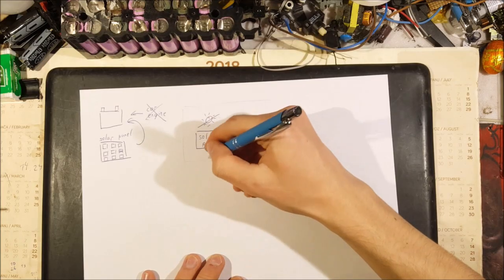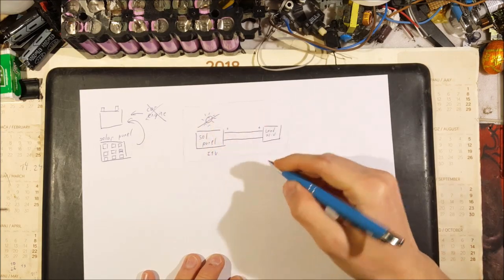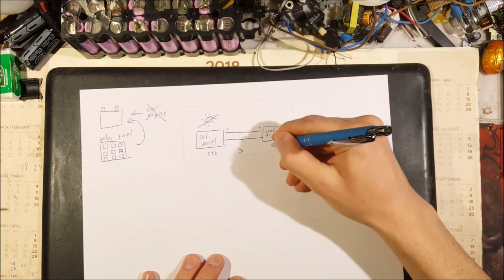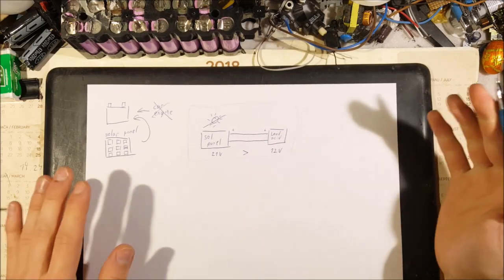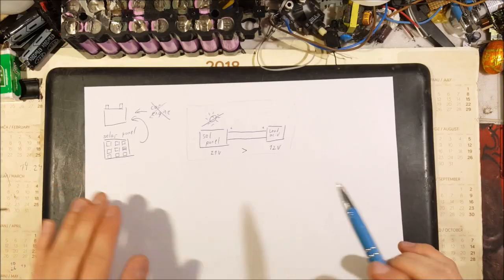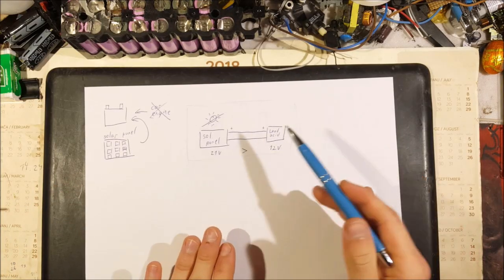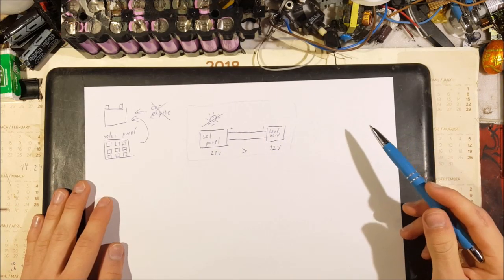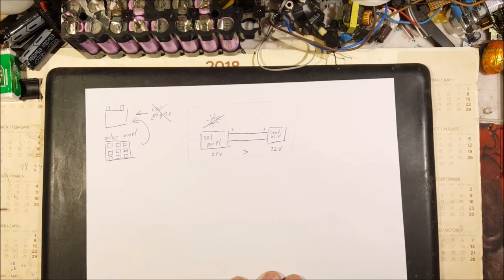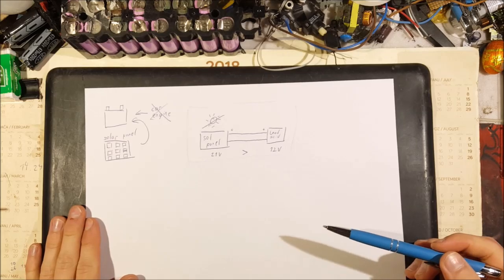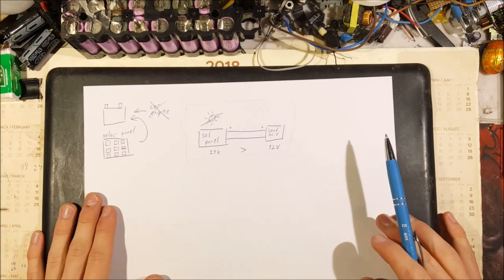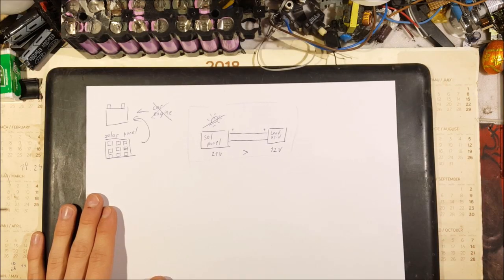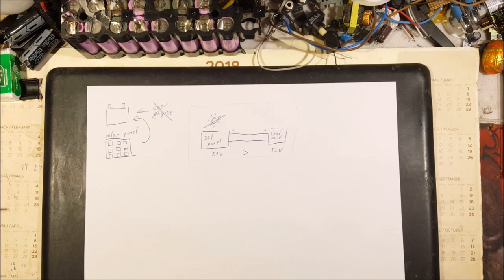And since 21 volts is more than our 12 volt lead acid battery, one would think that the solar panel would just charge the lead acid battery and we would all be happy. But wait, there is nothing to limit the current, which means that this circuit would not last all that long before something explodes.